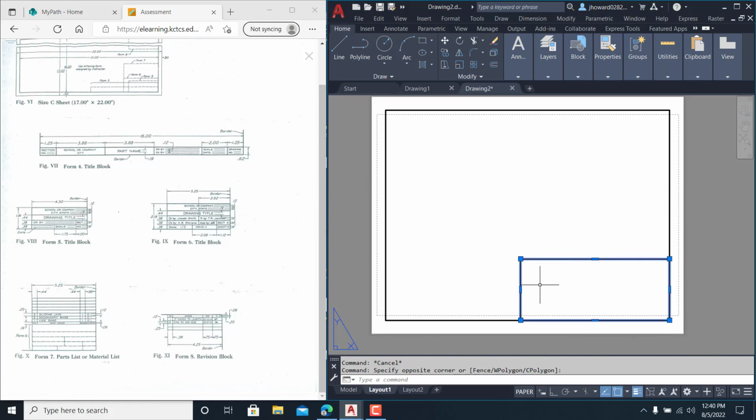This is polylines all together, so all I have to do is just explode it. And then I can just do some offsets, 0.38 from the bottom line there. Come up through there, then offset 0.44. And I missed a 3/8. You got the point of it. And then we had the offset of the 0.44.